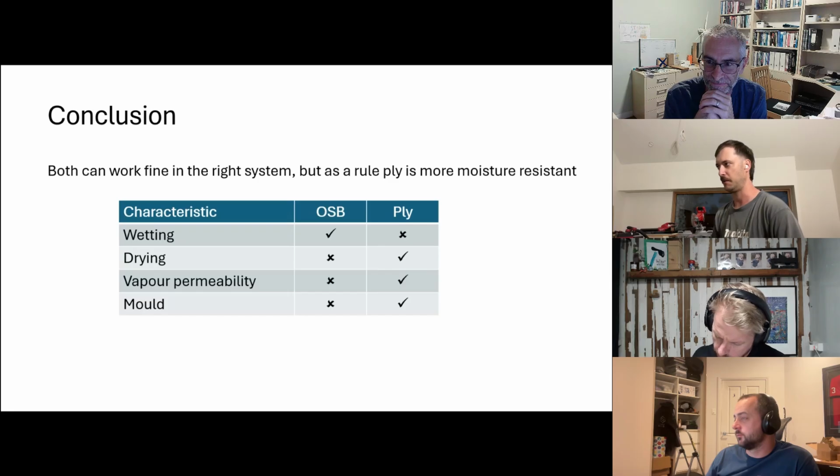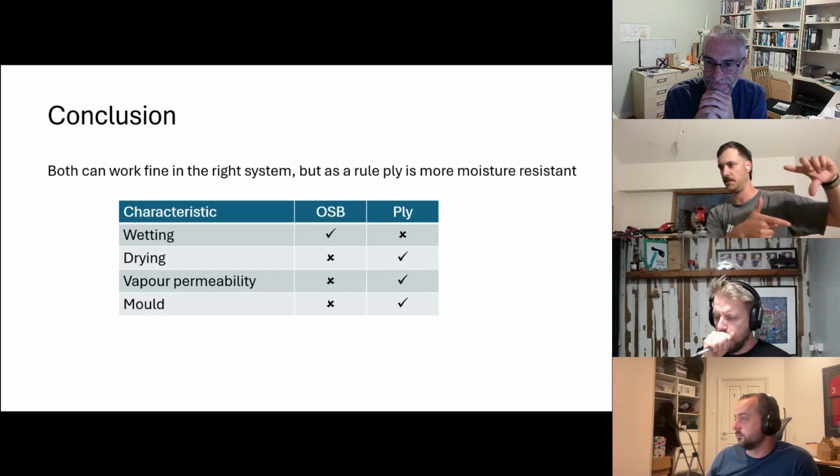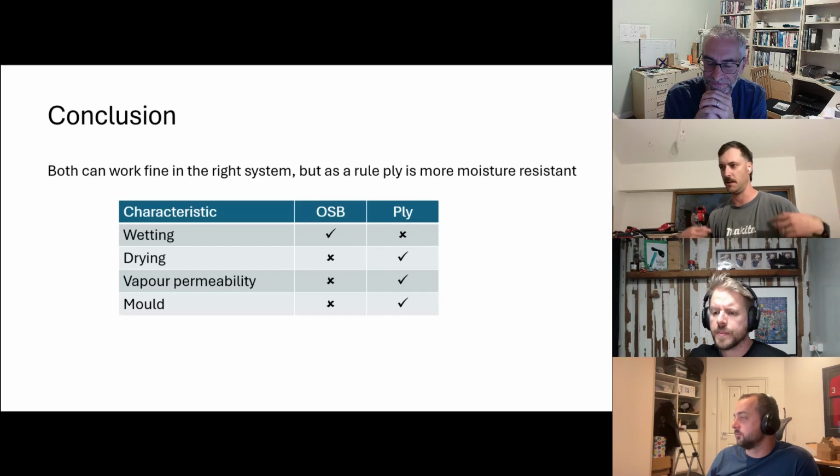For example, on my place, I've got cast iron vents every second brick to get the airflow in, and so I've got the actual airflow, but then that's 2 courses up, and then 2 courses down, I've got my weep holes for drainage. But it's just something you don't see often at all. Because it's bricks, we forget about it.